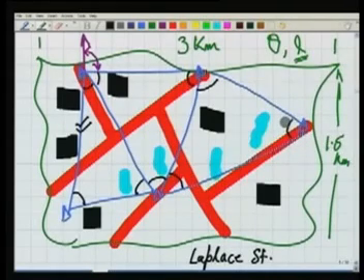We start from the measured base length, with all the angles known, and compute this length. Now this computed length can also be measured in the field, and the measured length and the computed length should agree. If they do not, our survey has some problem.